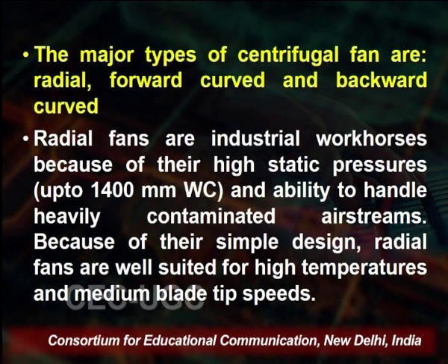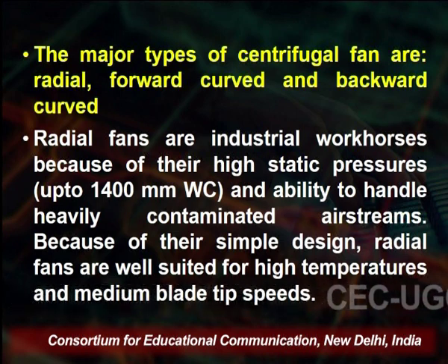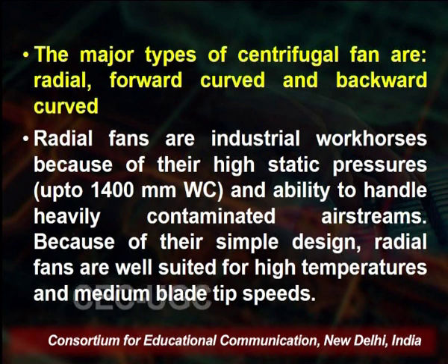So, the major types of the centrifugal fan are the radial, forward curved and the backward curved. Radial fans are used in industrial workshops because of the high static pressure and ability to handle heavily contaminated air streams. Because of its simple design, radial fans are well suited for high temperature and the medium blade tip speeds.